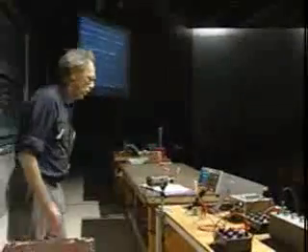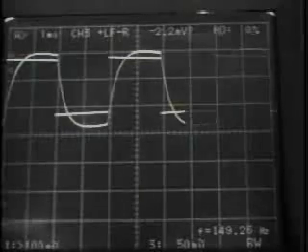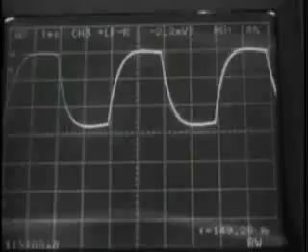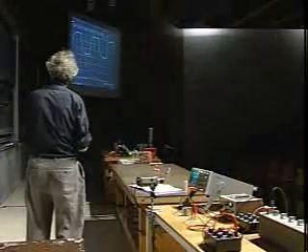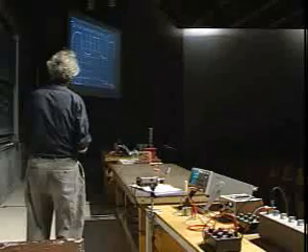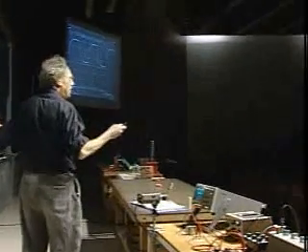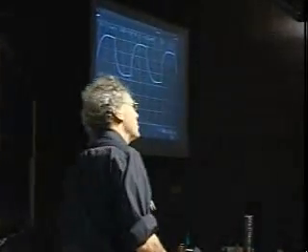And now I'm going to show you the voltage over the capacitor, and I will take the other one out. And here you see indeed exactly the image that we discussed. So you see early on the charging of the capacitor, and it reaches effectively the maximum value. You don't have to wait infinitely long. We say infinitely long, but clearly if you wait 3, 4, 5 times RC, then you're almost there.